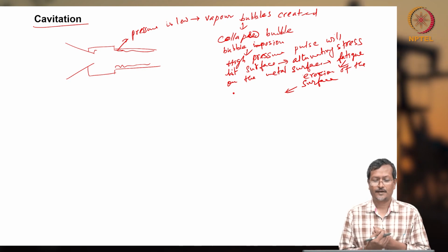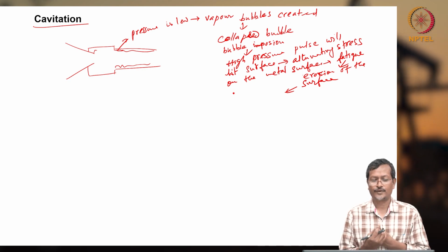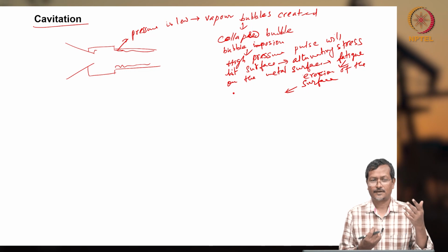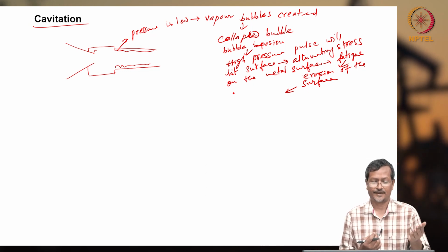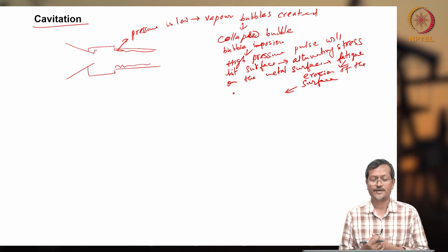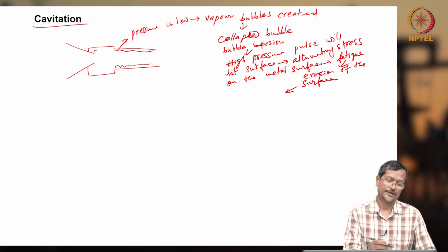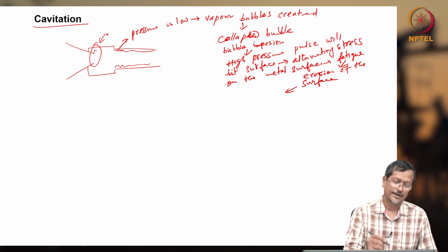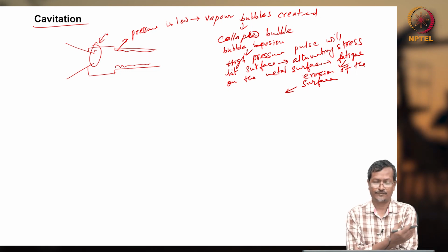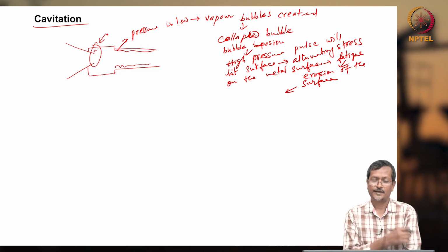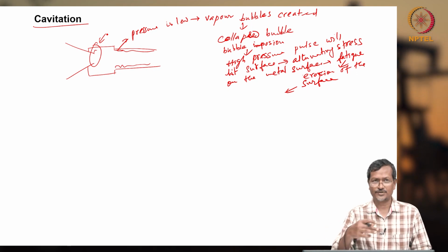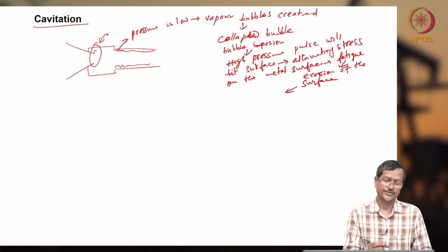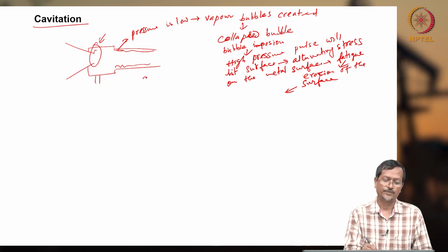Okay, and if you add a moving element, for example a hydraulic engine pump, the life will be lower. But in this case, life is definitely higher. But one main problem is that its efficiency is very low because of this nozzle. Okay, nozzle discharge coefficient, CD, some CD value will be there. There are losses, mixing chamber losses, suction chamber, diffuser, everywhere there are losses. So with all the losses together, the efficiency will be 30 maximum.